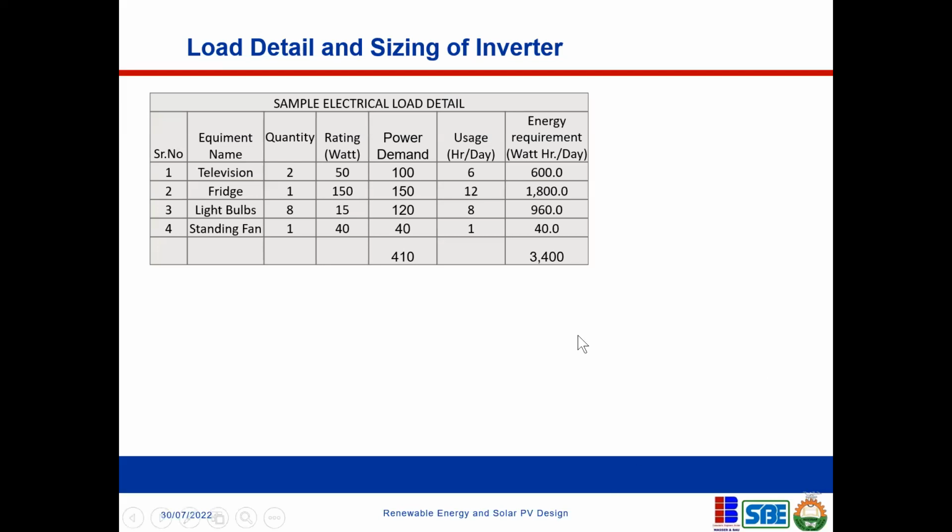So it's important to understand two important things: the power requirements in terms of the peak demand and the energy requirements. These are the two basic things that you need to know: the power requirement and the energy requirement. In our first class, I had explained the difference between these two, and they are not the same. Most times, even we engineers misuse these two terms. They are not the same. So you need to understand them. And doing a simple energy audit will help you to determine what the power requirement and the energy requirement would be. And that's what I have done here so far.